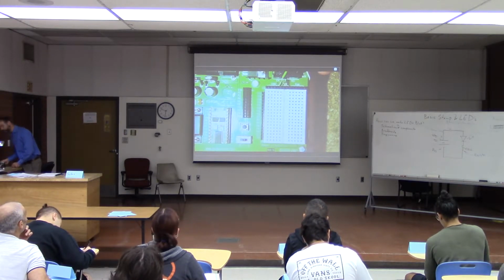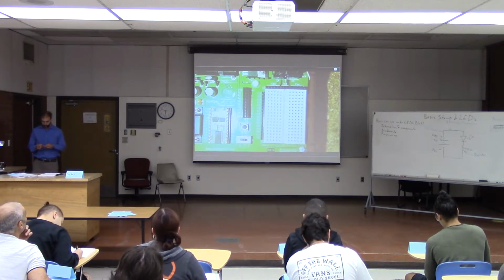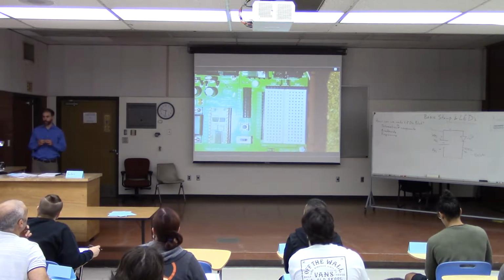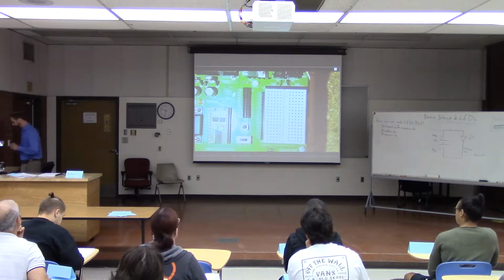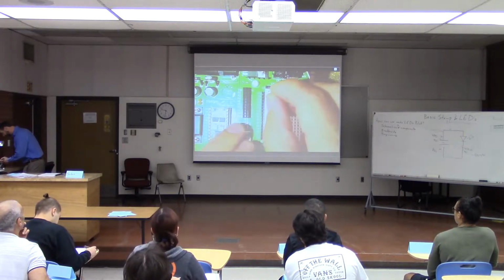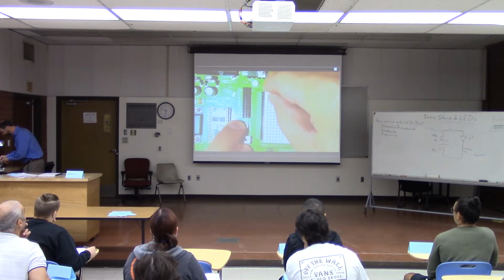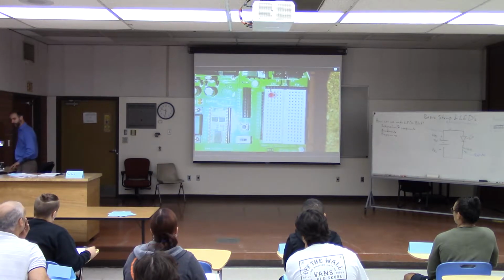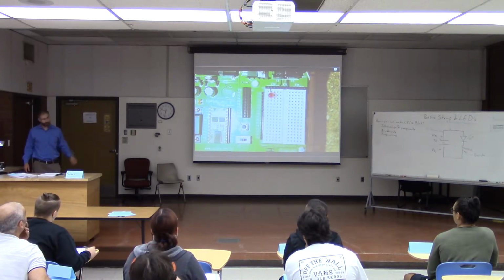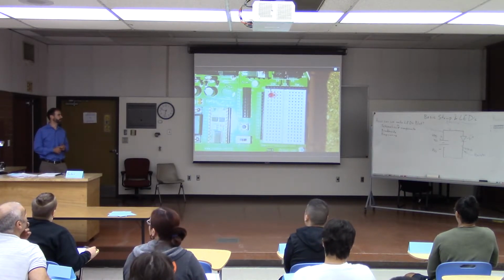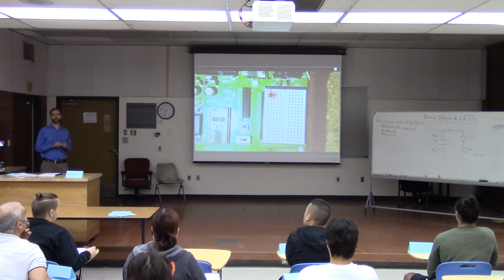5 black holes there. So what we're going to do is plug the anode of the LED into one of those 5 black holes. Okay? And then the cathode is just going to go to any place that you want on the breadboard, because we haven't connected that to anything yet, right? So we made our first connection. We've connected the anode of the LED to VDD. Any questions about that?